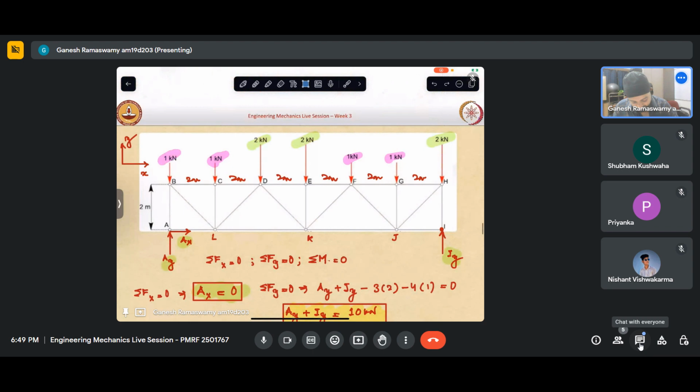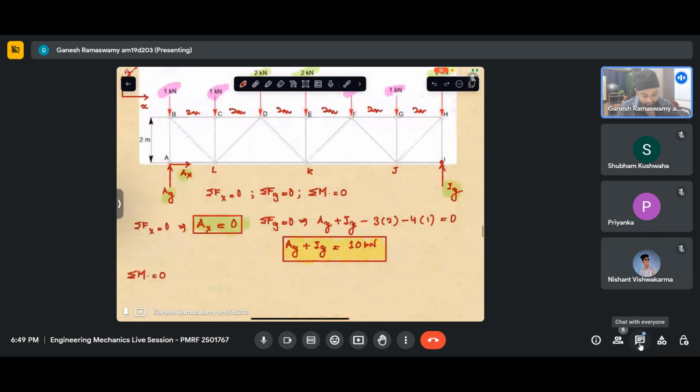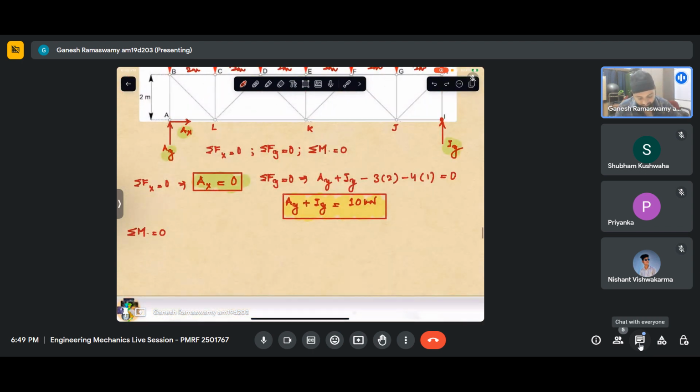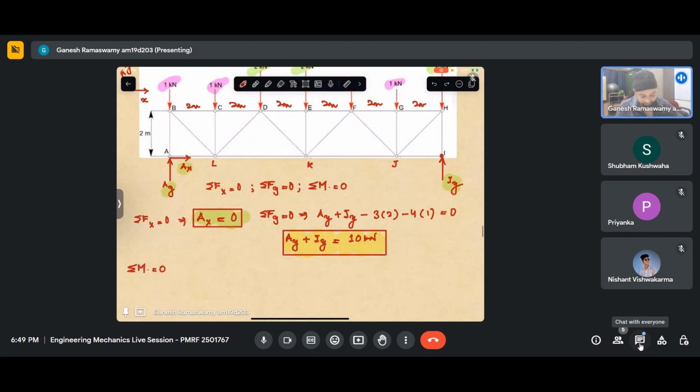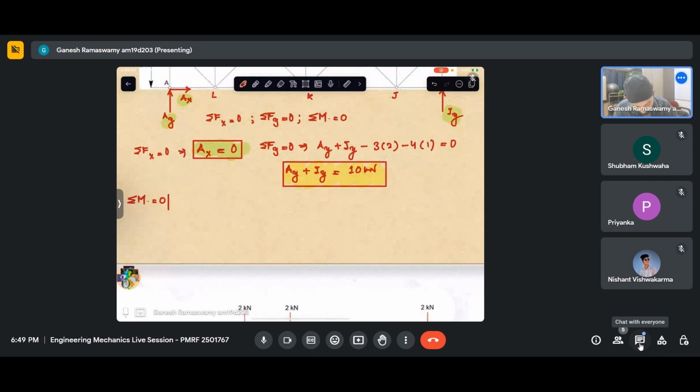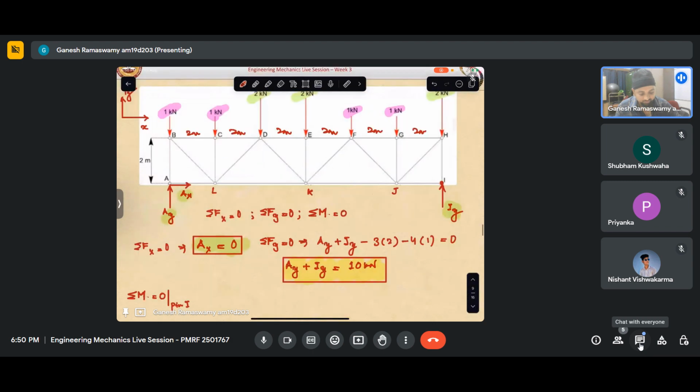And this being the xy plane, any anti-clockwise moment would have its axis parallel to the positive z-axis. So in the equilibrium condition, all anti-clockwise moments will be positive and all clockwise moments will be negative. Ay will have a clockwise contribution about I. So let us take this about point I, or pin I I should say. So this will be minus Ay into what is the total distance? It is 12.